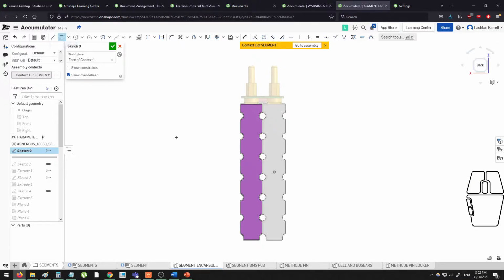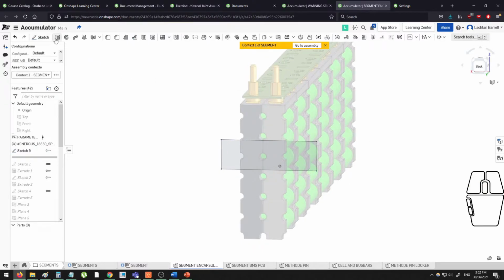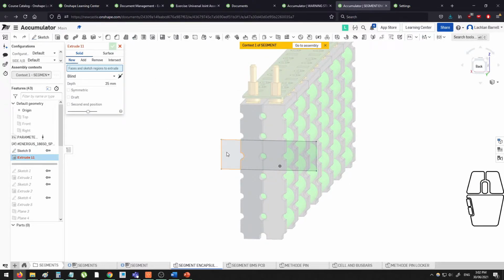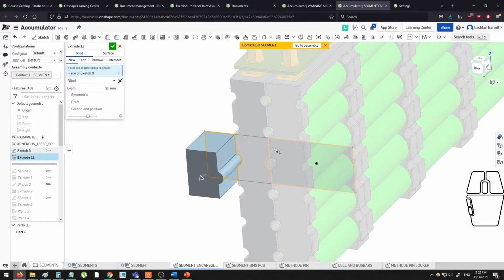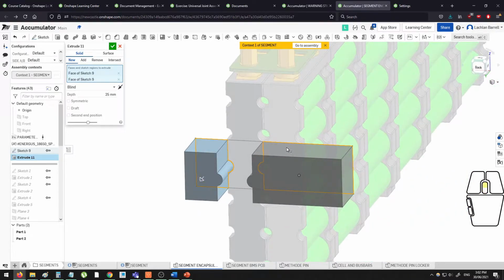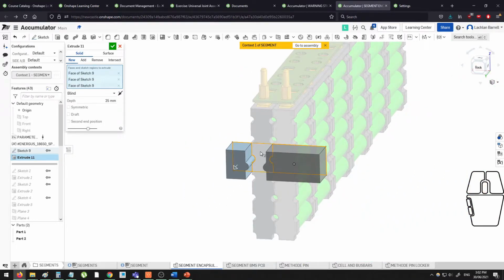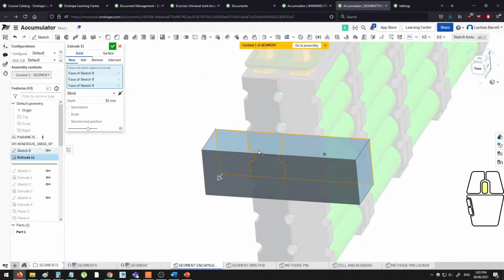Anyway, so if I then draw some geometry, not really important what it is, and I accept that. If I then want to extrude that sketch face, and I try and select it, you'll notice that it kind of uses whatever your original sketch face was as a bit of a reference, whether you want it or not. That can get very frustrating.